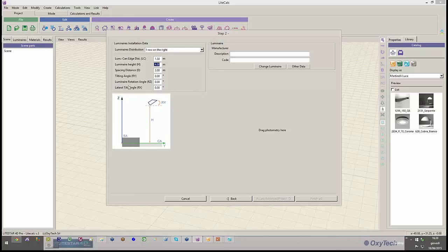In this case, we do not consider this; we consider these values in case you have to rotate the luminaire. Why? Because sometimes you may have some luminaires which are not perfectly positioned. It means that the photometry, for example for an asymmetric luminaire, is not in the proper plane, which is usually the C0 plane. It is placed on the other side. So through this parameter, you can rotate the photometry 180 degrees.